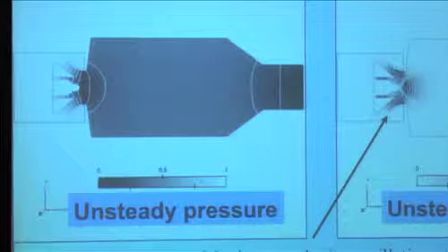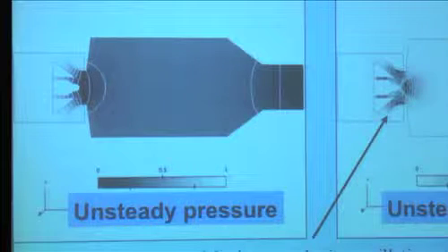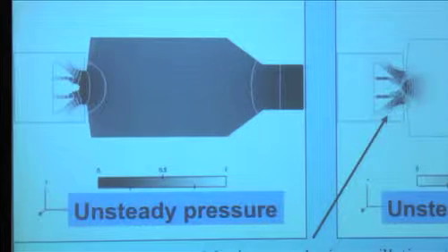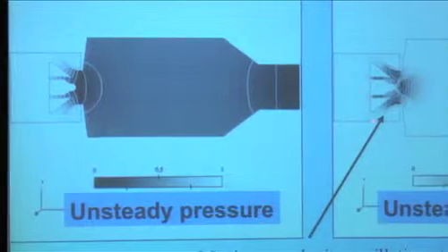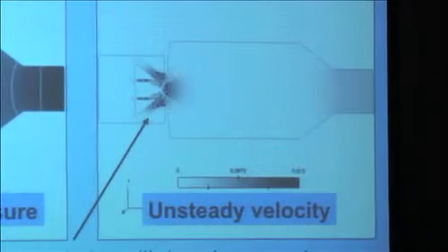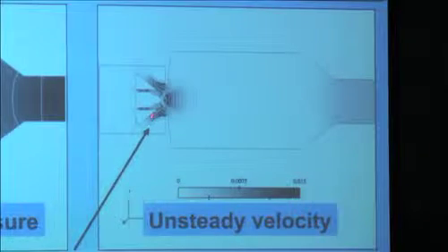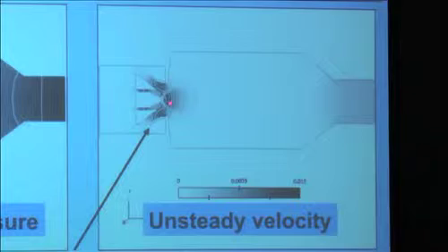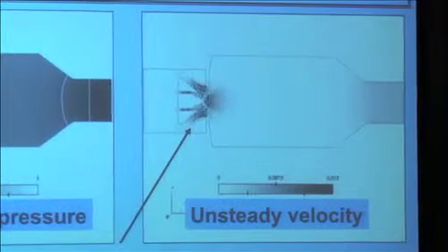And the guy said, well, it's always his fault, okay? And the guy said, well, I don't know, let's go back, take a look at the results. This is the result of AVSP, of the acoustic code. Look at that, of course, when you look at the unsteady velocity, you see it's very large here. That makes a lot of sense that it's large here. It's the sensitive place for combustion. You'll have large velocity fluctuations. So this is consistent with what we see in the experiment.